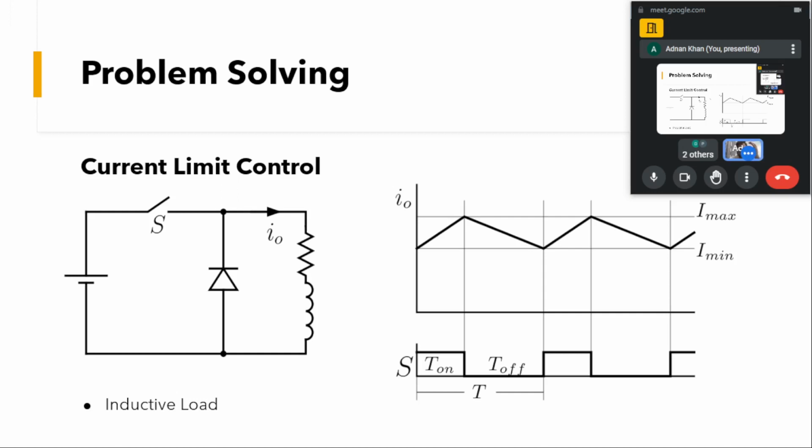Or if you were able to break the current, we would get such a huge voltage spike that it could damage our system. So from that equation we know the rise in the current will be gradual. When we turn on this switch, the current through this will rise to some point.